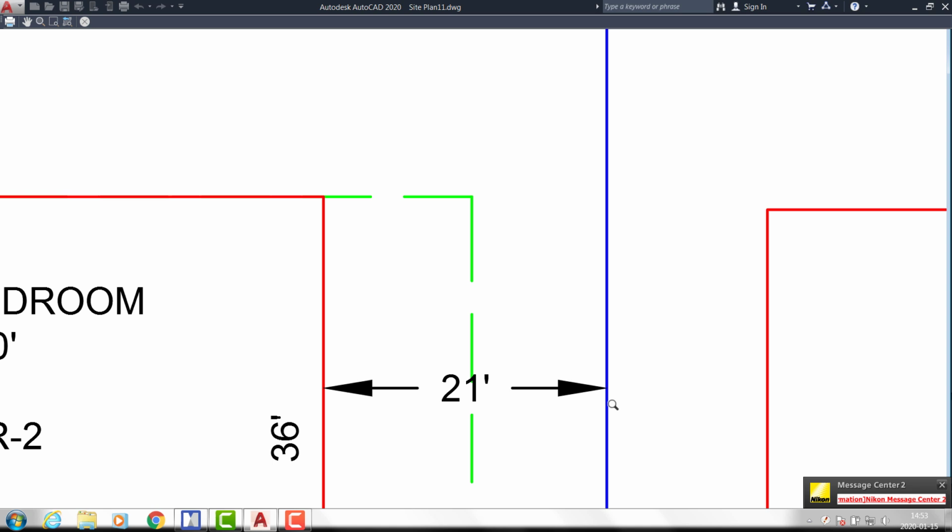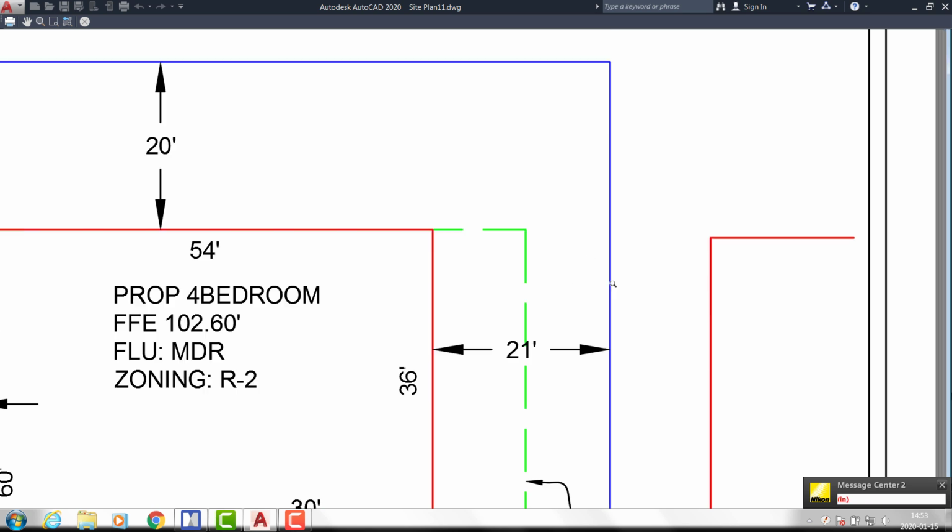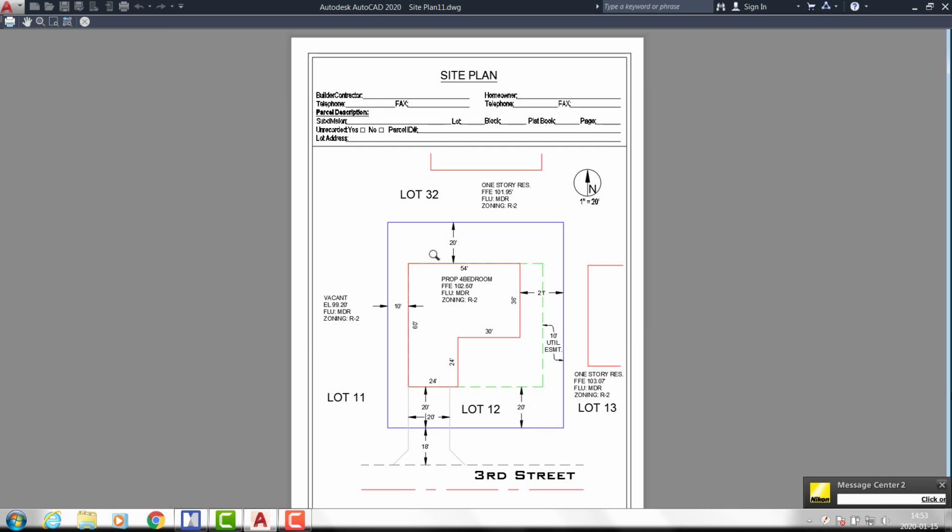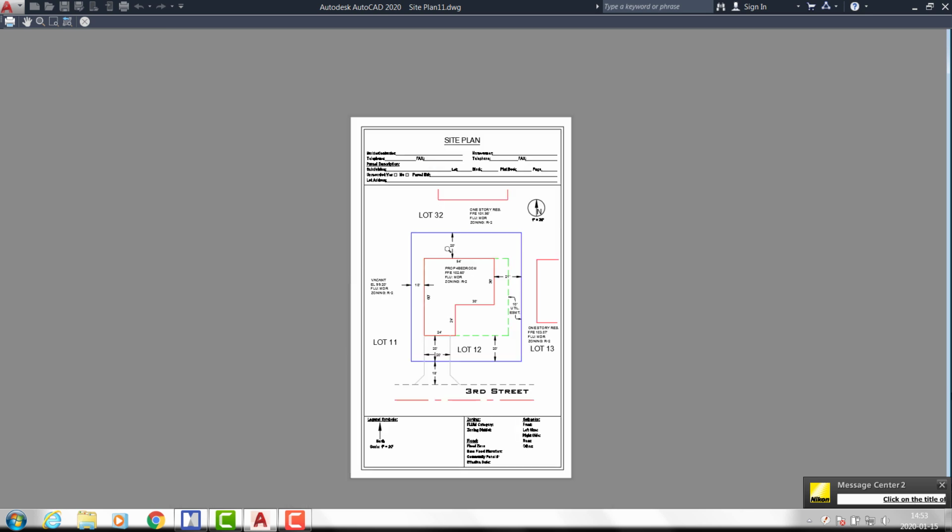What you will notice is as you zoom in, there's line weights that are being applied. And so that's why the lines get thicker as you zoom in. And so they're maintaining their distance across the page relative to the scale of the dimensions of the piece of paper. So when you say it's 0.25 millimeters, it's actually going to measure 0.25 millimeters across the piece of paper. So that's the desired output.